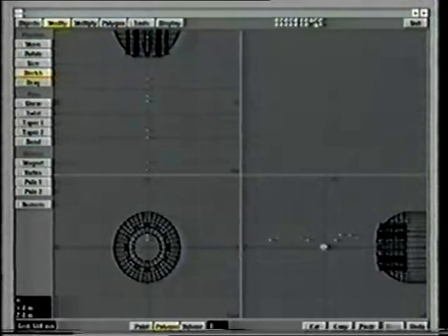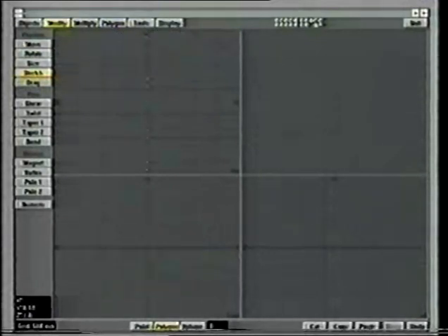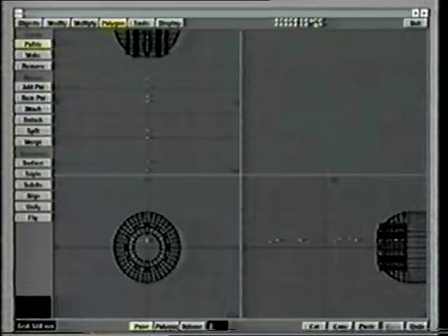And using the control key to constrain the stretch to one axis only, I'm going to stretch it down there like that. Now all I need to do is create the center for this, so I need to make a few more points here. So let's create one on the 0 axis there, one on the 0 axis here, and here, because I want to have a recess in the gun barrel, which is about there.